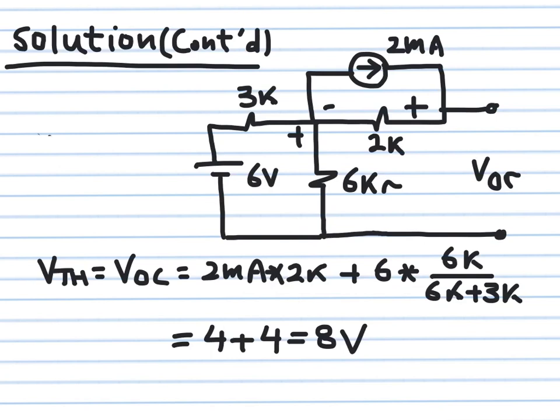Second step is to find the input resistance seen into this one. And as we did before, you have to remove all the independent sources, make a voltage source short circuit, make a current source open circuit, and then see the input resistance looking into this side. This circuit does not have any dependent sources, so I can calculate the resistance directly. I don't have to connect an external source and then calculate the external current. So I will make this one open circuit, I will make this one short circuit, and then I'll try to find the input resistance. Let's see how the circuit looks after we do that.